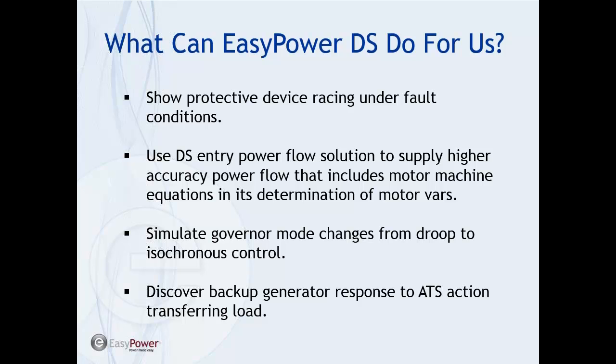Next, we can use stability, the power flow, right when we enter stability, and we'll talk about that. The power flow solution will give you higher accuracy in terms of how induction motors respond to voltage conditions and the VARs that they draw. That's a really interesting thing there.